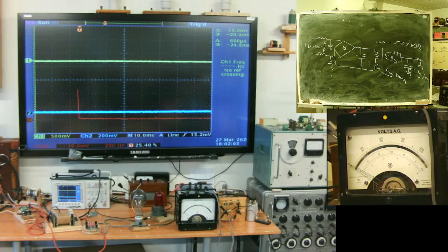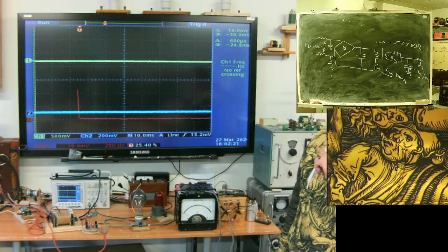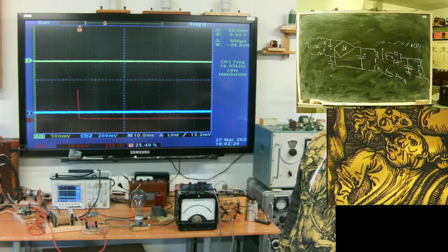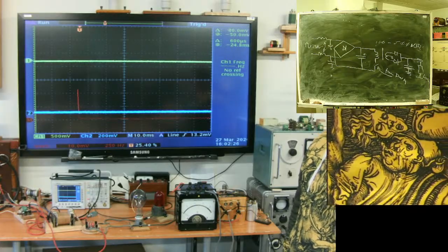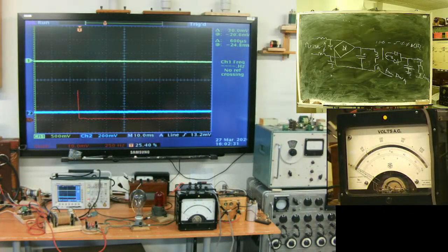Why is it harsh? Because I don't have the inductance of a transformer before my rectifier. That's why the current pulses are so sharp. Okay, but here we see the case of a single phase load. What about polyphase loads? What about three-phase? It's more complex.